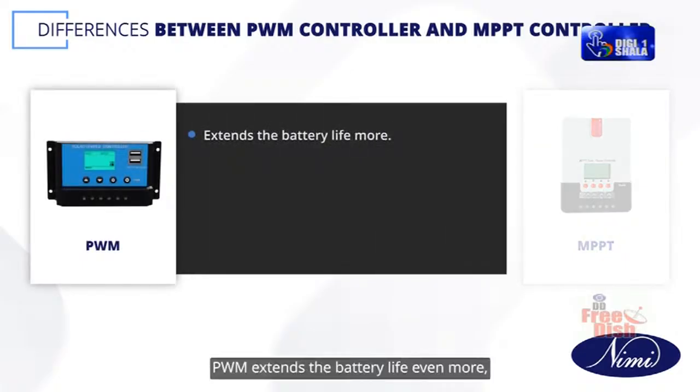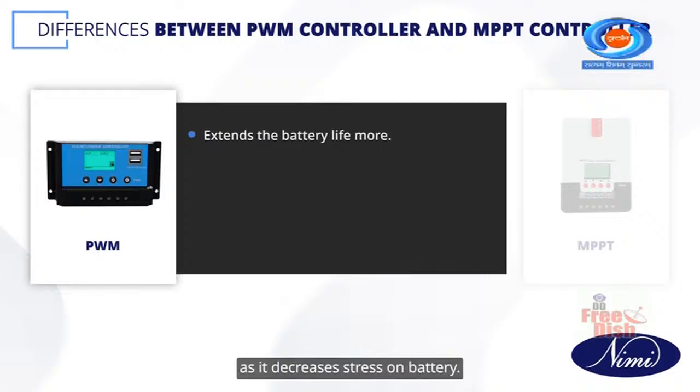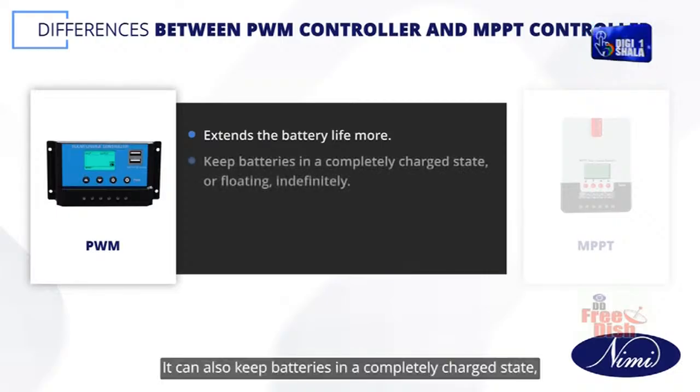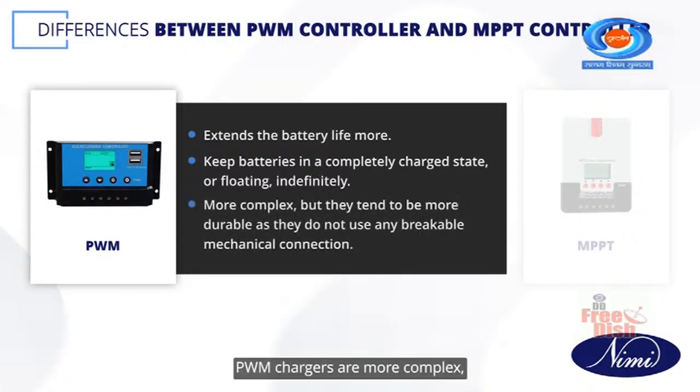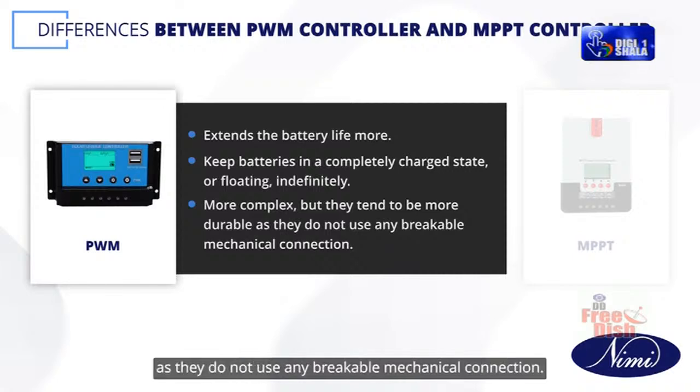PWM extends the battery life even more as it decreases stress on the battery. It can also keep batteries in a completely charged state or floating indefinitely. PWM chargers are more complex, but they tend to be more durable as they do not use any breakable mechanical connection.